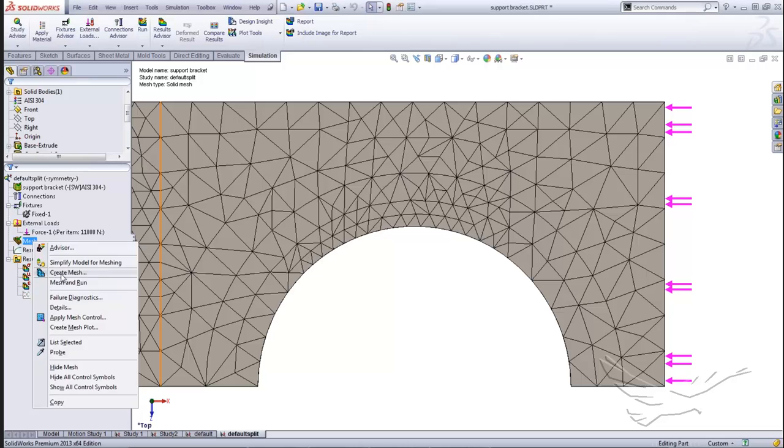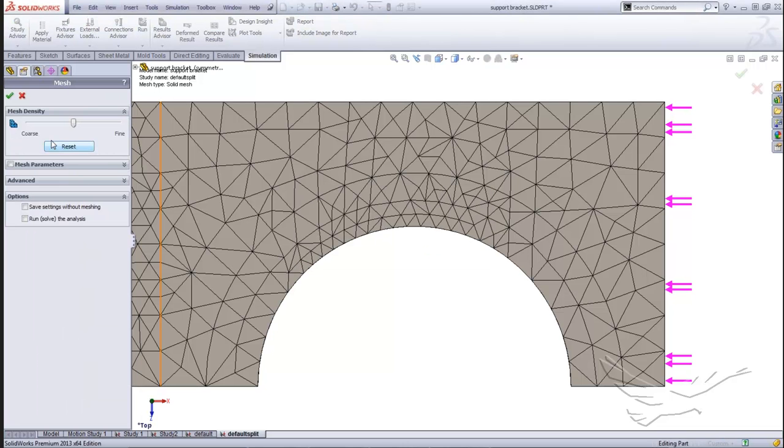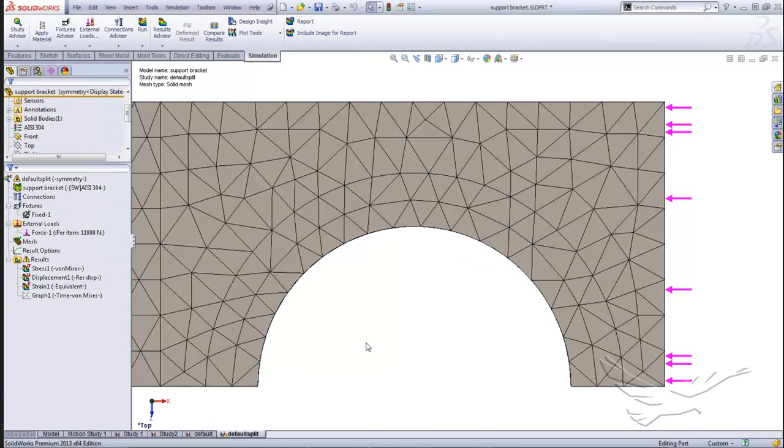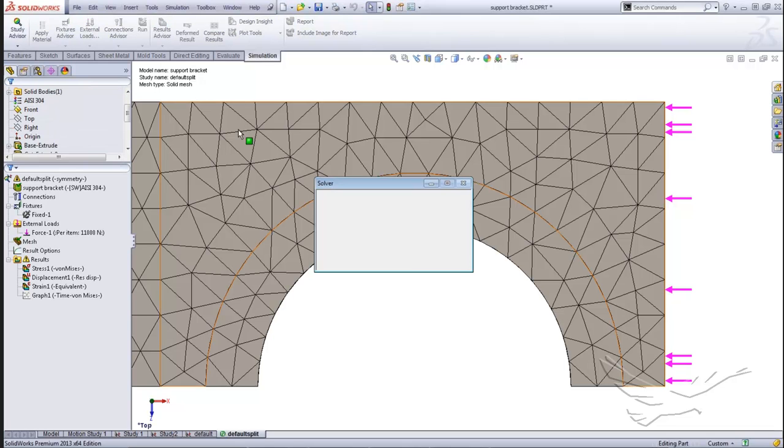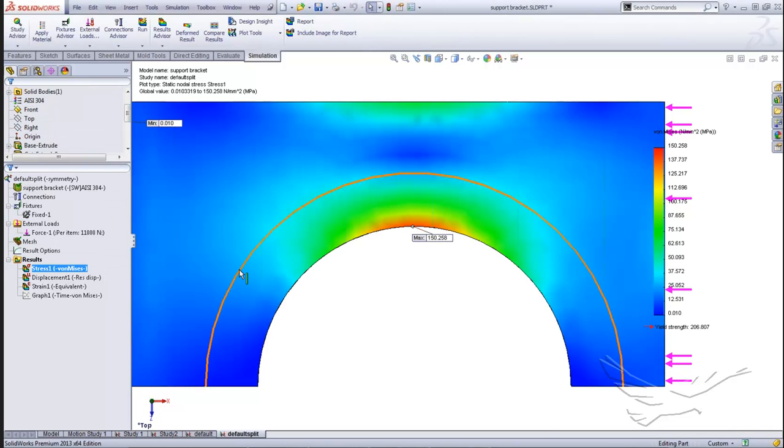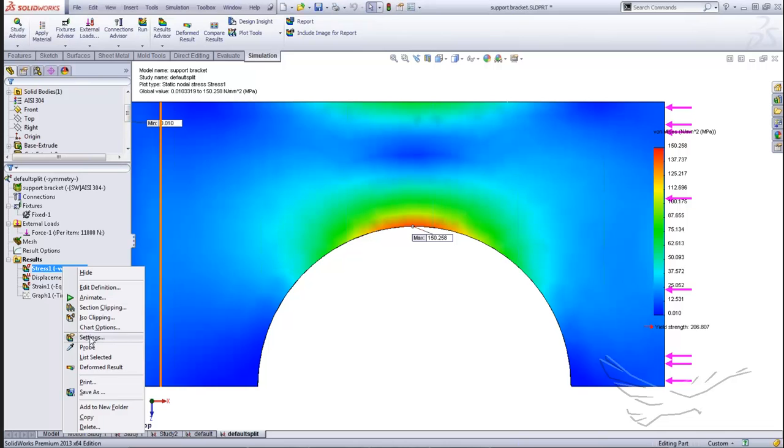Okay, so let's go ahead and create our mesh here. I think this one's a different mesh. Let's just go ahead and create a standard mesh. There we go. So you can see now we have two elements before it gets to that edge, and it's much more uniform around that cylinder. Also, the benefit of this is it actually places the nodes at those locations.